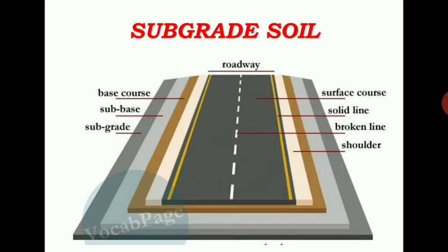Usually you have seen the formation of waves, corrugations, rutting and shoving in blacktop pavements, the phenomena of pumping and blowing, and even the consequent cracking of cement concrete pavements, which are generally attributed to poor subgrade conditions. So the formation of waves, corrugations and rutting that you can see on pavements is because of poor subgrade conditions.